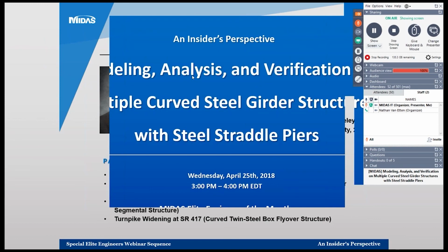Okay, the next question: did your support springs for MDX change between dead load and live load analysis? And did they also change per deck placement sequence due to changing composite properties? Yes. We looked at three conditions: a dead load only spring condition, a live load only spring condition, and a 1000 kip vertical load spring condition. We noticed that yes, they did change, but the changes were very, very small.